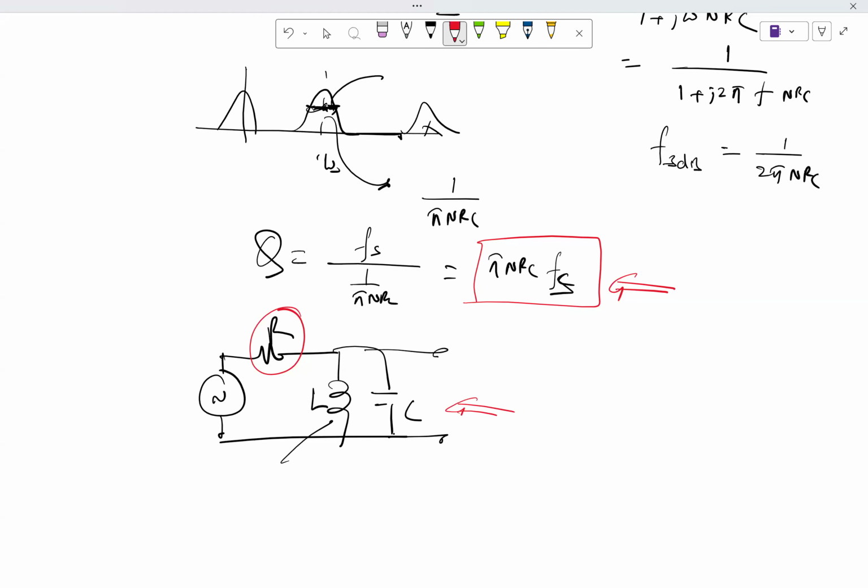But in our case, where we have frequency translated effects, essentially what did we do? We created a low pass filter at a small frequency and we upconverted its response to bandpass. Because of that, your bandwidth is not dependent on the center frequency. Because the bandwidth is not dependent on the center frequency, if I keep increasing the center frequency, your Q factor increases. That is a good thing in narrowband sharp bandpass filtering. So these are the main applications of N-path filters, where they trump the LTI equivalent.